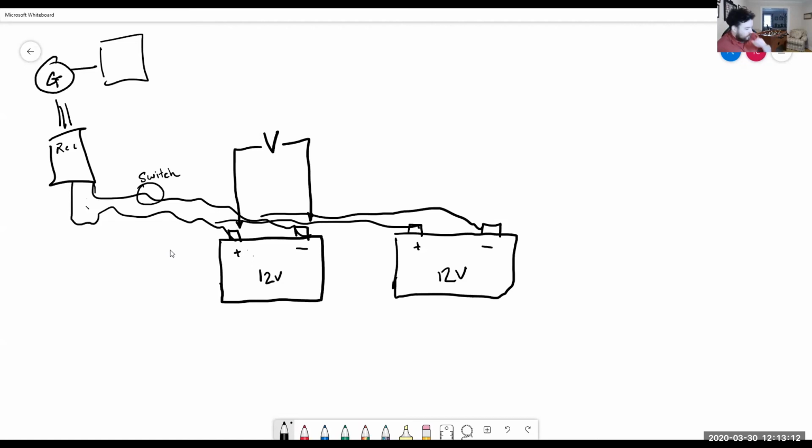Most ships I've been on, emergency generator rooms will have a switch, like we said, with an option of 1, 2, 1 or 2, or off. And most times it's all switched to 1 and 2. And then most generators will have basically a light switch. You turn it on or off. If it's on, you're charging your batteries, or if it's off, you're not charging your batteries. So, sorry guys, generator's still running.